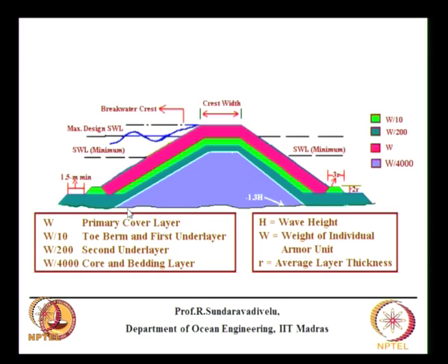No means why we cannot use? What are the factors you have to consider if it is in Guwahati, which will govern the design? Somebody said soil, soil is one consideration, what are the other things? Climate. Earthquake, that is the main parameter. Guwahati is in seismic zone 5, Chennai is, I think, in 3, so the force will be enormous. Similarly wind also will be different, so we cannot use. Same way here also, depending on the seabed the foundation requirement will be different.